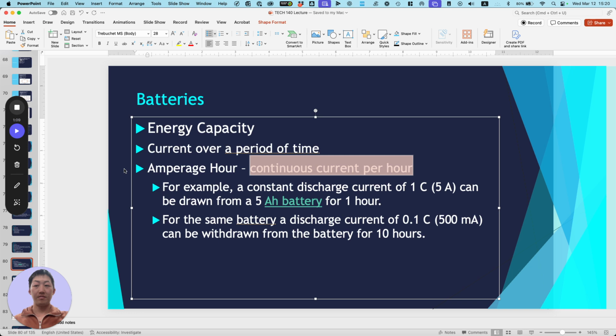So yeah, you can see there's 2 plugs in the front and 2 balance leads. So that way you could do a split screen. You can charge 2 different batteries at once. Now, do keep in mind, like what I was showing you here, your power output is still the same. So if you're charging 2 really large batteries, it may need to reduce the power output to each battery, meaning it's going to be a little slower than if you were to charge 1 battery at a time.